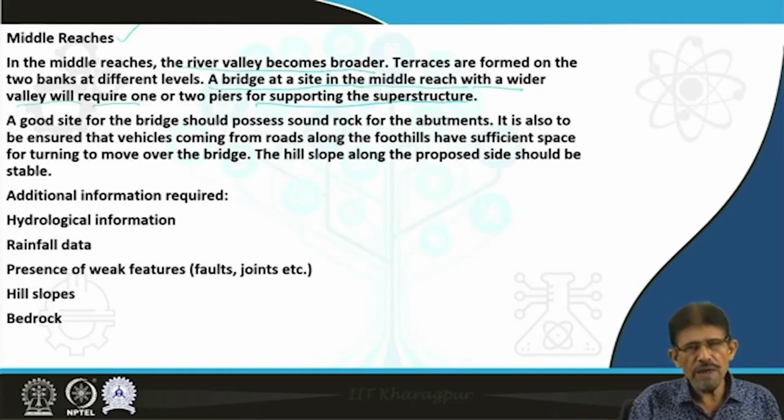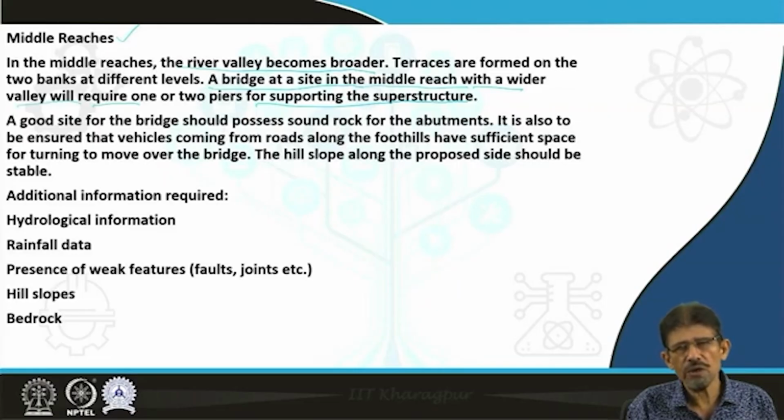The middle reach is actually a good site for bridge construction if the rock exposure lies at shallow depth. If the rock lies far below the upper soily layer, then construction of bridges in this area is problematic and requires more money for various investigations and modifications in design.